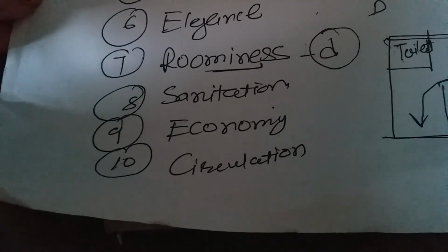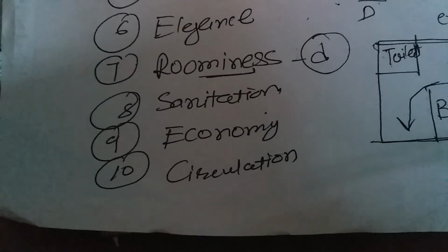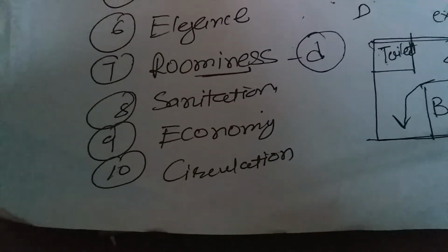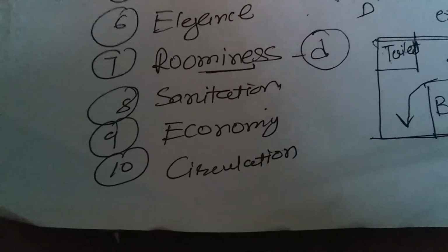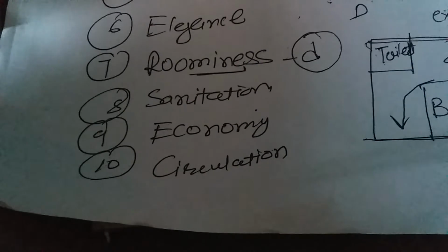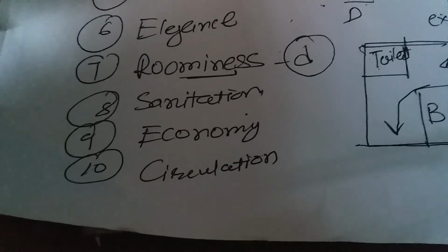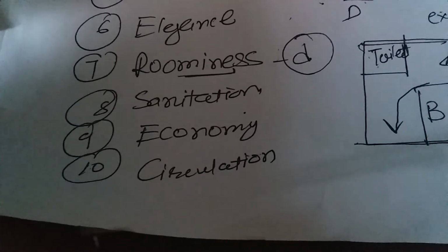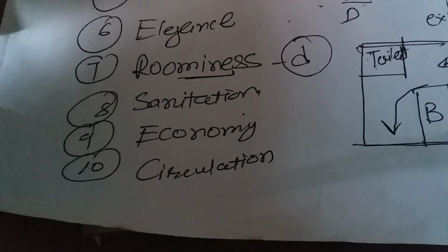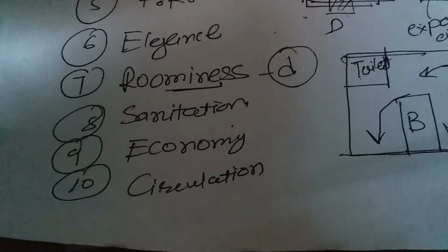Very good lighting promotes hygienic conditions for the accommodated persons, which increases the working capacity, accuracy, safety, and finally a pleasing environment for working. Good ventilation is an important factor for comfort in a building. Poor ventilation or lack of fresh air in the building produces headache, sleepiness, tiredness, and less concentration on work. In sanitation, there are two types of ventilation: natural ventilation and artificial, meaning mechanical ventilation. In natural ventilation, fresh air is supplied into the building through windows and ventilators, whereas in mechanical ventilation, fresh air is supplied through fans and air blowers. Good ventilation is generally achieved by proper placement of doors, windows and ventilators.